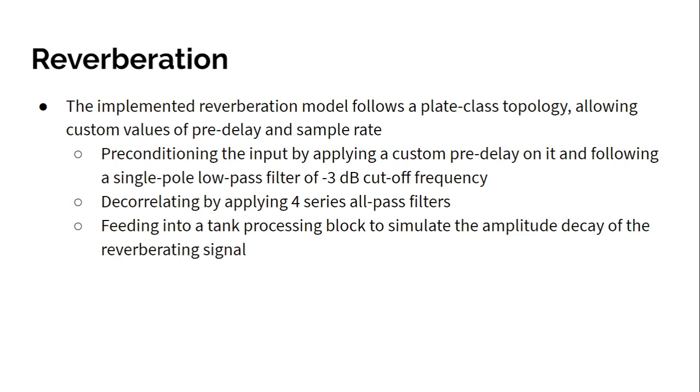The last channel modeling factor that I'm going to talk about here is the reverberation. It also has a very complicated and deep mathematical background behind it, so I'm not going to be too specific about the math behind it. But I have to say that the reverberation scheme used here follows the plate class topology and allows for custom values of pre-delay and sampling rate.